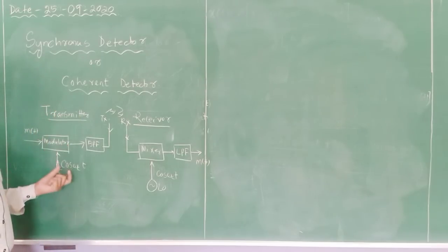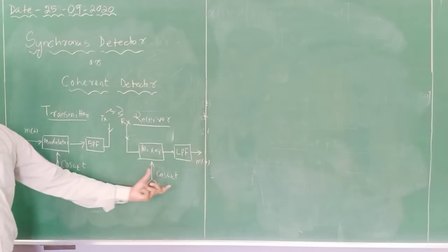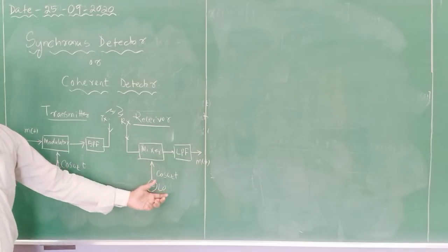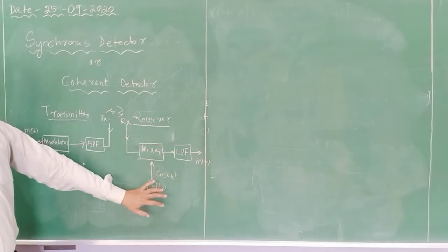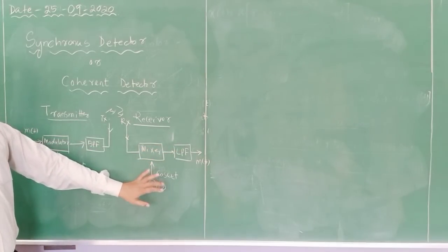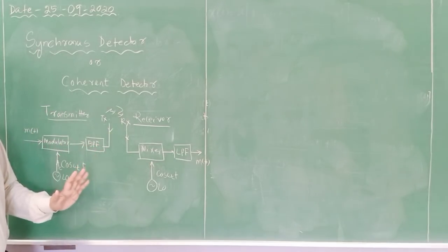If the same carrier frequency is used at the receiver end and demodulation is done with respect to it, then the whole method is called the synchronous detection method.